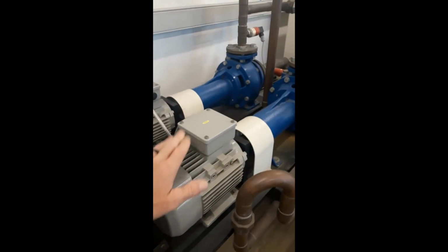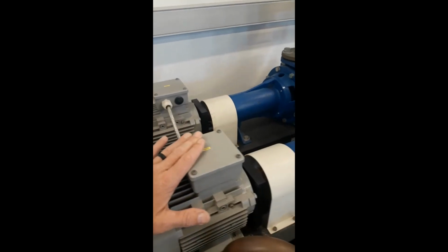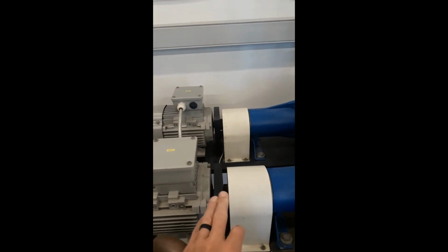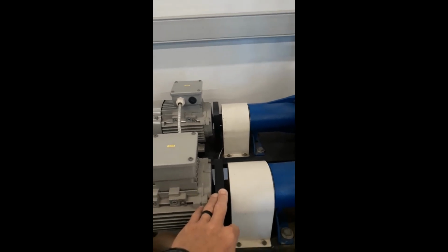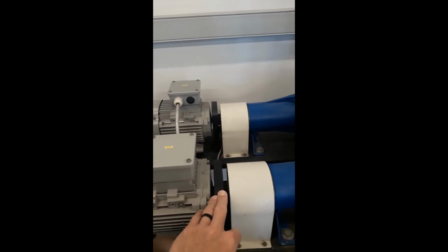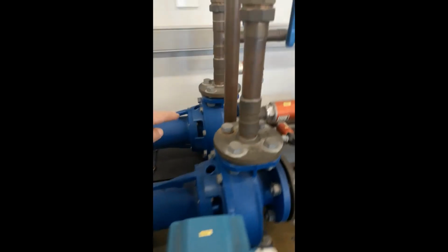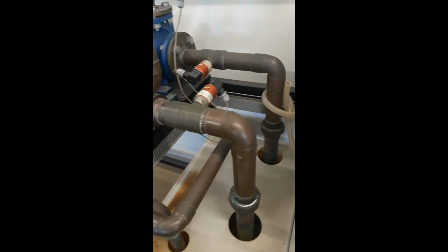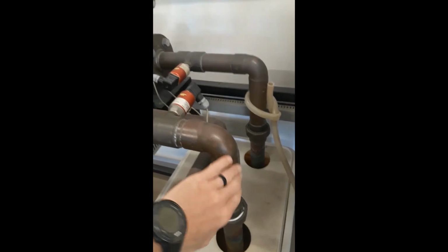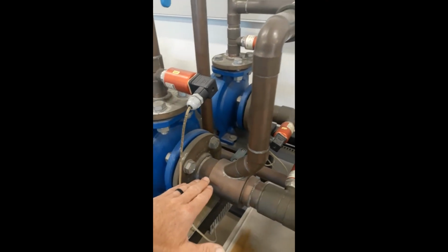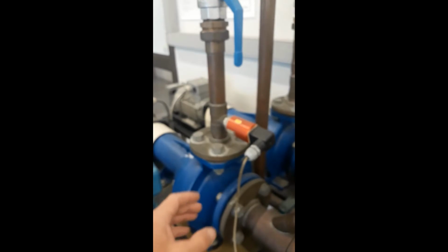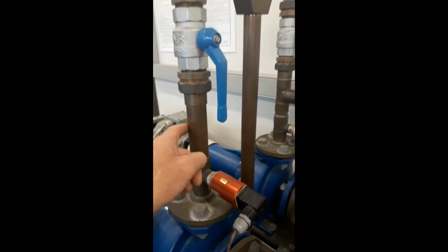We're going to measure the electrical inlet power, and then over here on the shafts, the speed, the RPM of the shaft is measured. And again, pump 1, pump 2, and these big lines, this is the suction lines, the inlet lines, and then these over here is the delivery lines.